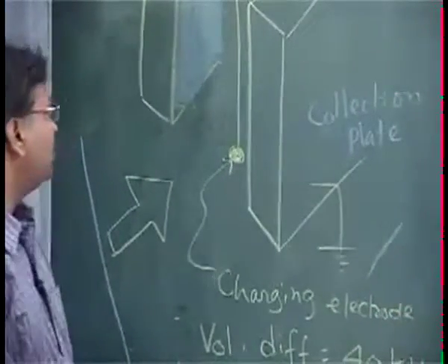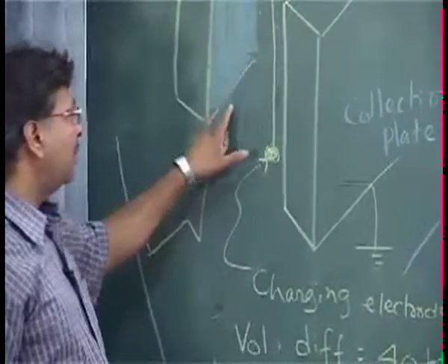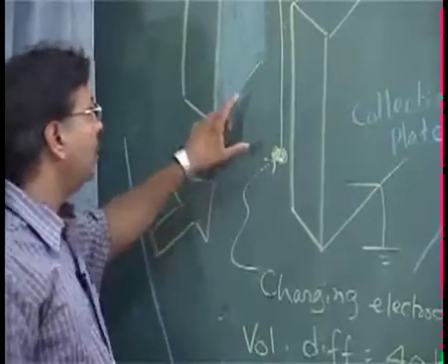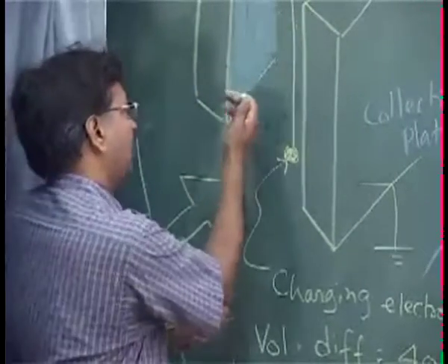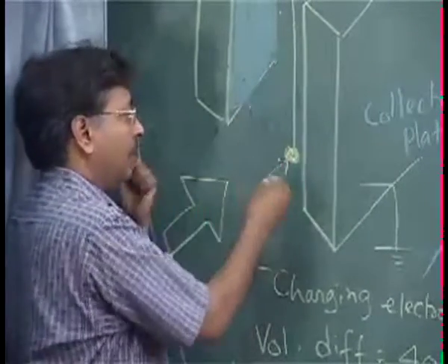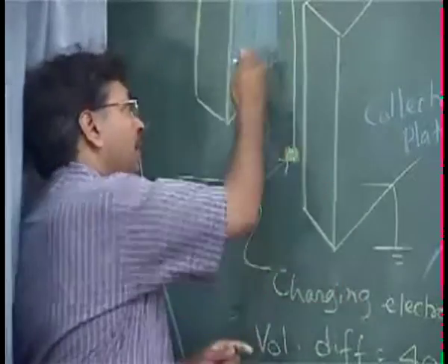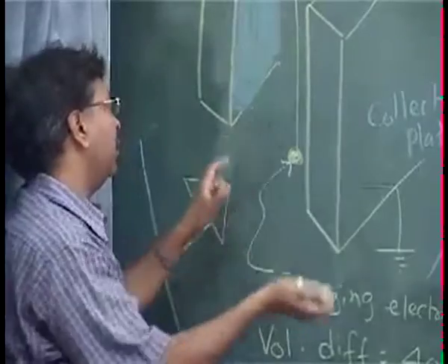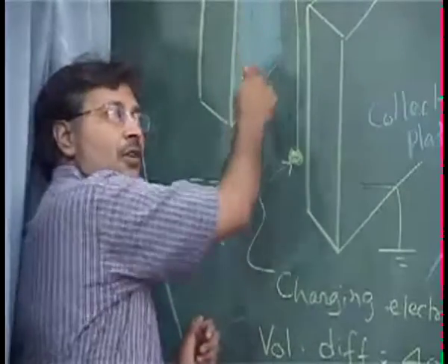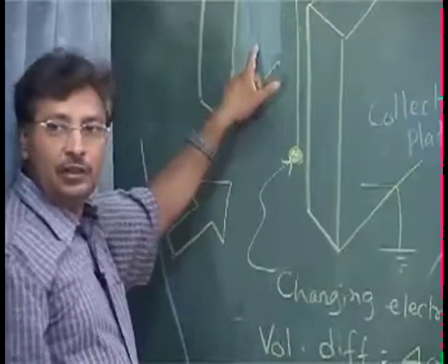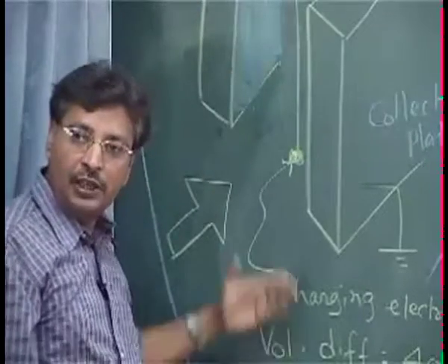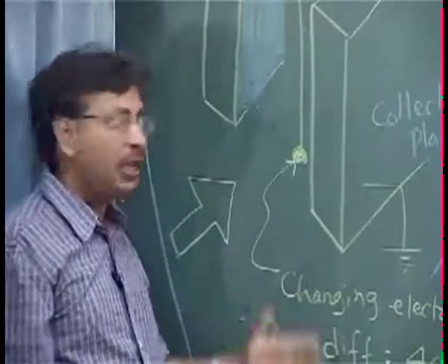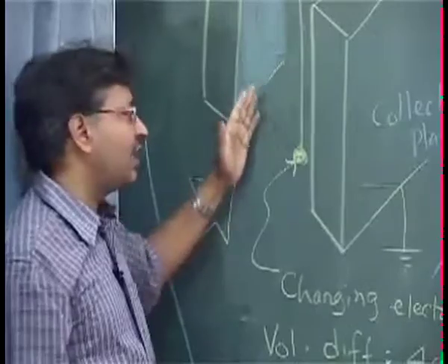What we do in the wrapping operation is, there is some kind of hammers, okay, which with some mechanical movement, can come and hit the plate very hard, then again they can come round and hit the plate, and once they hit the plate, the dust will fall in the hopper, okay. Otherwise dust can be sticky and then it is not falling.